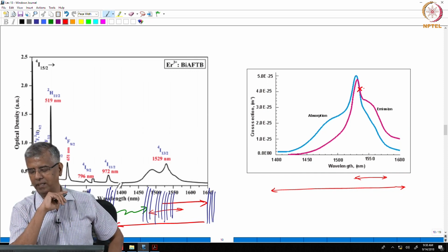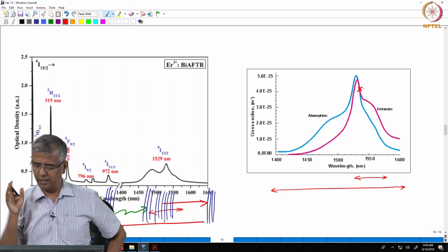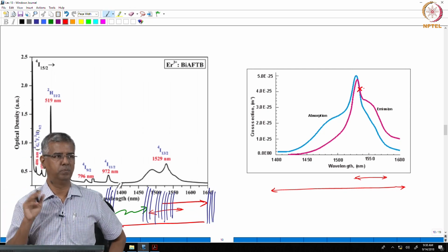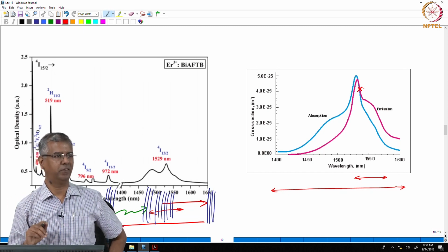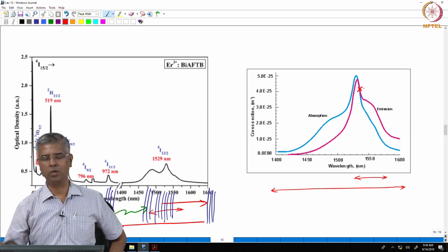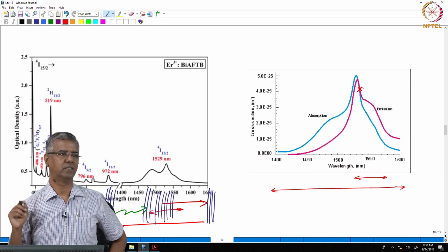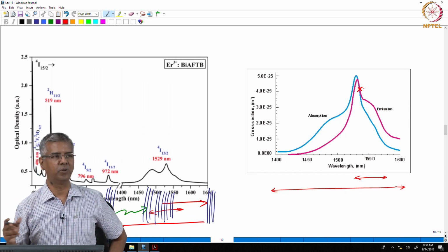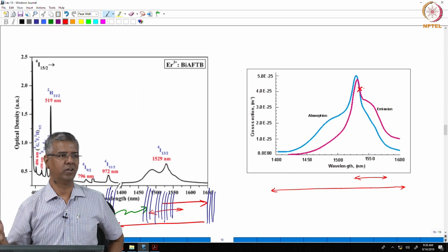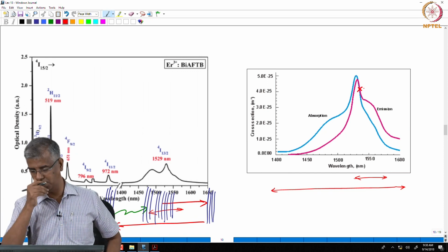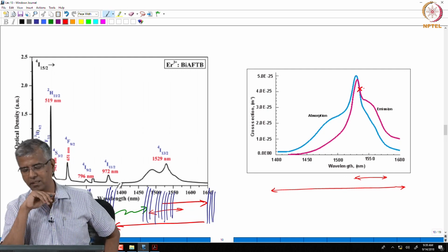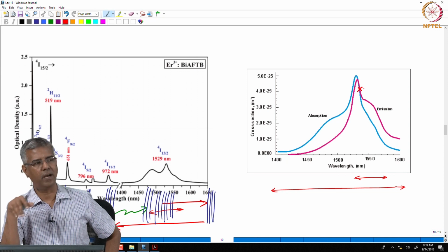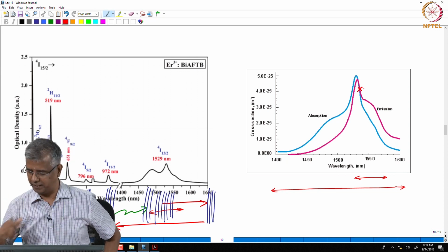What this also tells us is the absorption process is more probable at shorter wavelengths, and the emission process is more probable at longer wavelengths. So you are more likely to get gain in longer wavelengths. That's something that we were observing later on, but as far as how the signal is getting amplified, now we have to consider this in a little more detail.